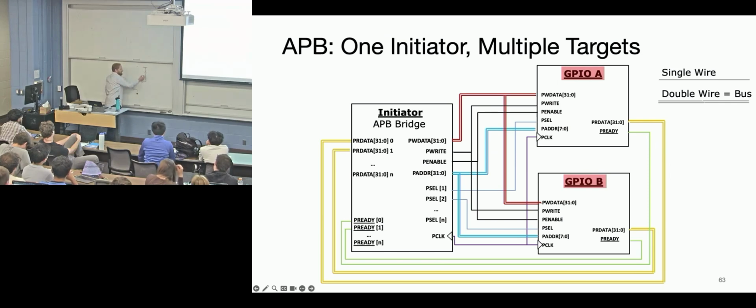How does it do it? Well, basically, say there is no current through here, then the voltage across this would be 0, therefore this voltage and this voltage are equal. And then if there is a voltage here, there's some current trying to pull this thing higher and higher. So the result is that if the switch is open, then this is going to be VDD. And if it's closed, it's probably going to be a stronger short than this big resistor, and it's going to pull it down. So if you can just intuitively play with Falstad and learn what this circuit's supposed to do, you'll be fine.